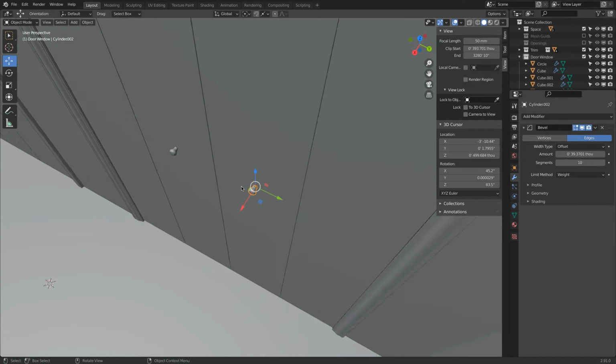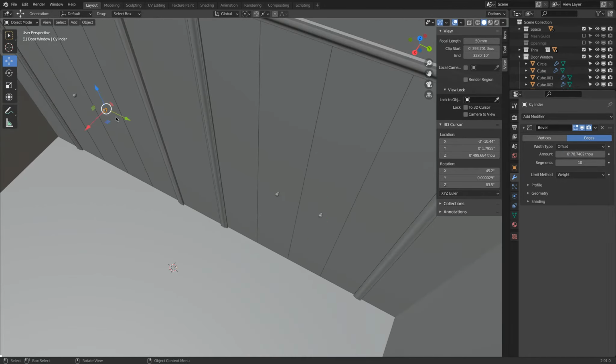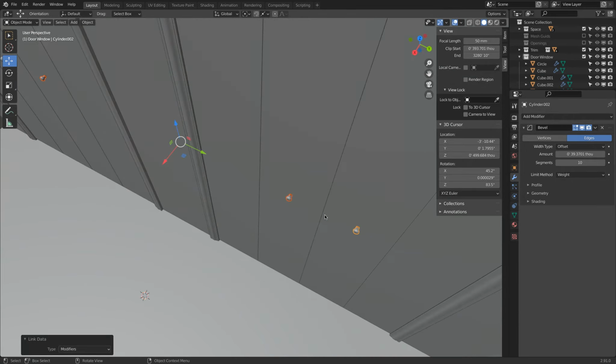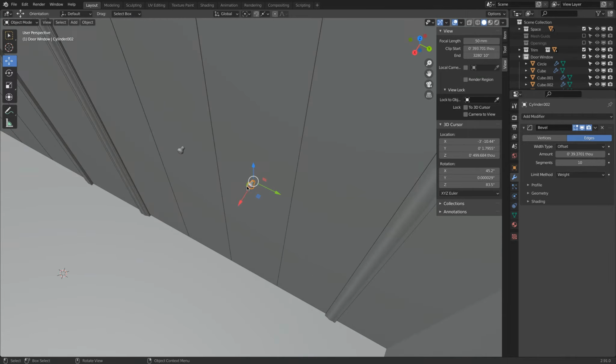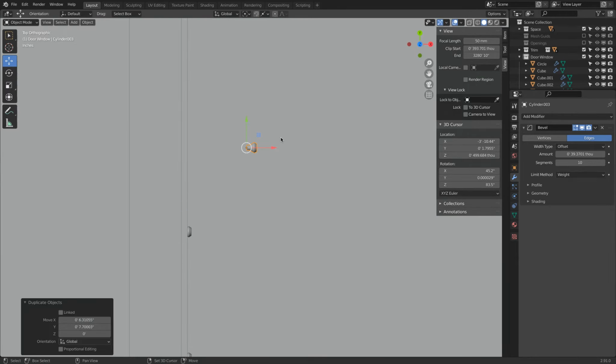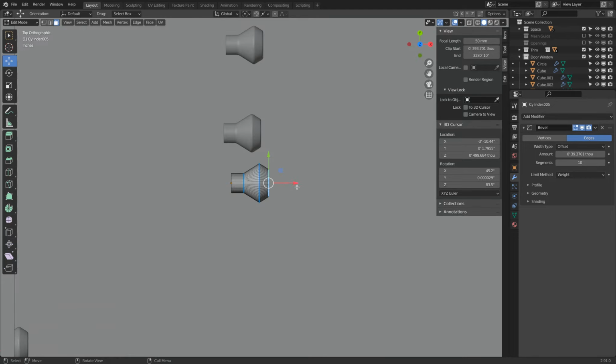Maybe I make the modifier tighter. I have to do the same here. So for this is my last one. Here I changed the modifier, Control L, and say link to the modifier. So all the changes are updated. Pretty cool, no? Another nice thing is I could Shift D and Shift D, Shift D, yeah, that's correct, Shift D. I'm making now on purpose actually variations.